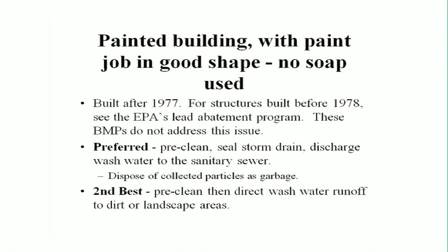There are seminars all over the United States on how to handle structures and remove lead-based paint. So you need to go to one of them, and we're not going to address that. But if you test the top surface on a home and it shows negative for lead, you might need to check on that building and see if there are 3 or 4 layers of paint. And if you're going to be removing any paint, you need to check the layers under the top layer to make sure there's no lead hidden under lead-free paint on the surface.